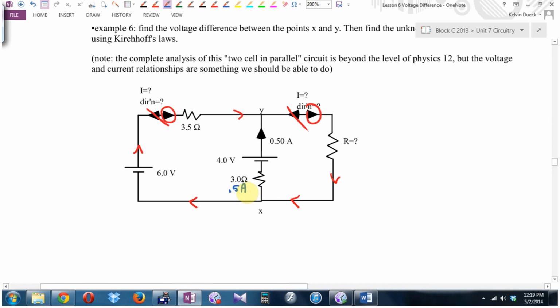Hey, I know 2 things on that resistor. I know 3 things. What's the voltage drop in that resistor? In your head, what's 3 times a half times 0.5? What's half of 3? Okay, I lose 1.5 volts. Let's go skiing.